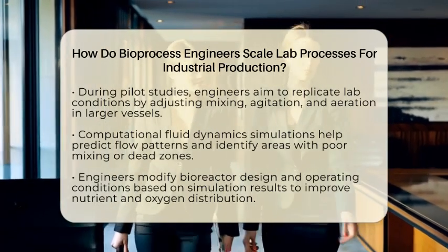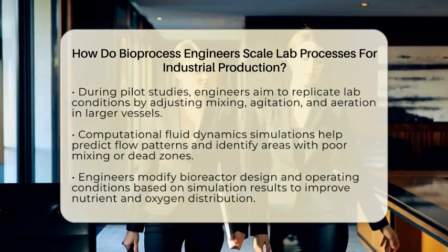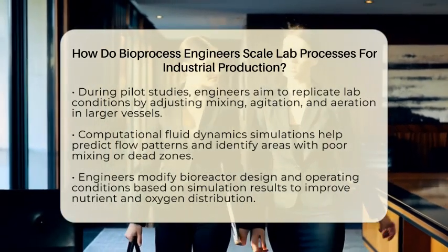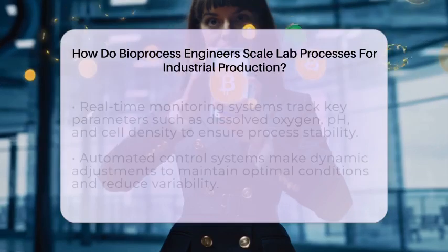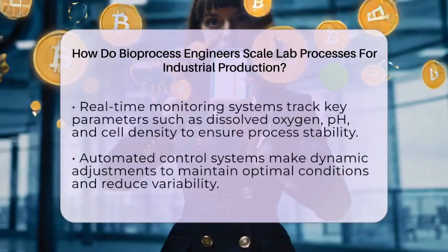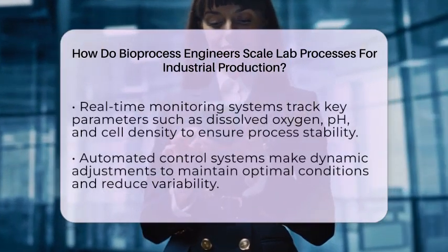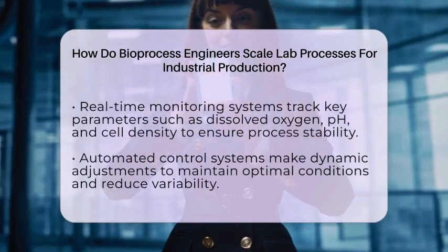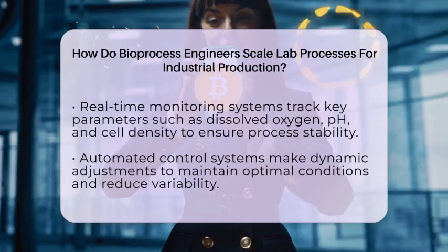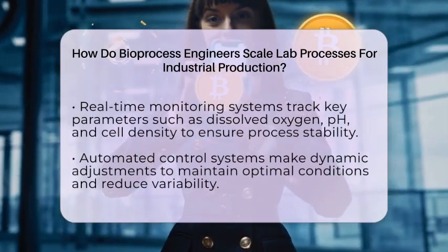A key challenge in scaling is ensuring uniform distribution of nutrients and oxygen throughout larger bioreactors. Engineers utilize computational fluid dynamics simulations to predict flow patterns and identify potential dead zones or areas with insufficient mixing. Based on these insights, they modify bioreactor design or operating conditions to optimize mass transfer and ensure cells receive consistent nourishment.